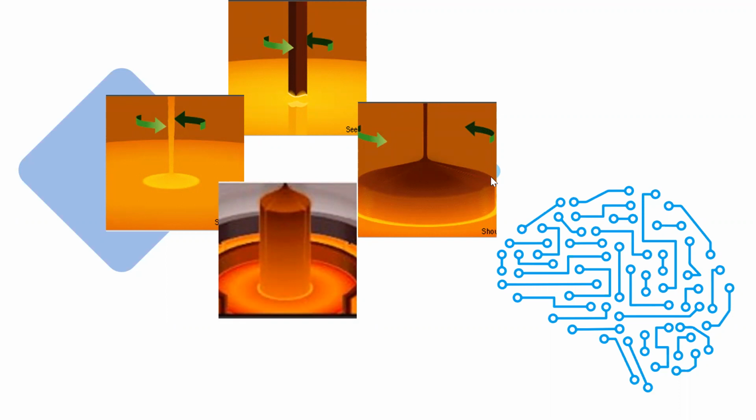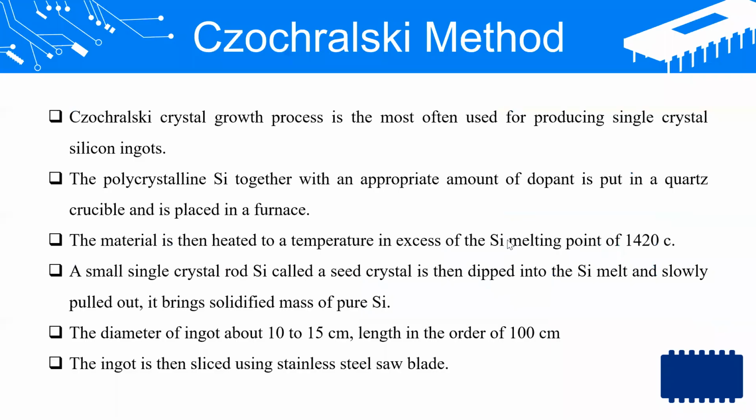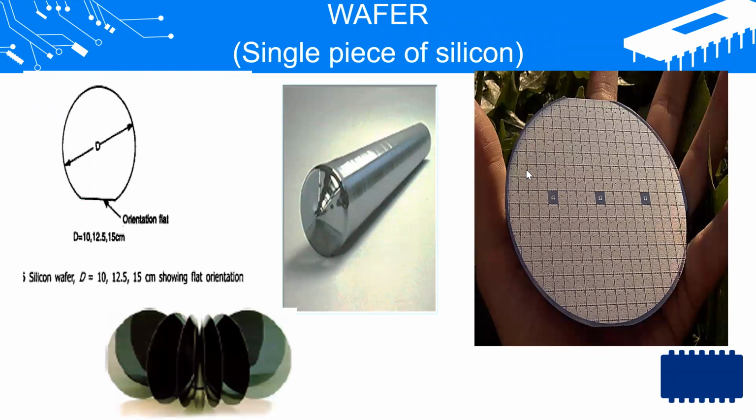The slices of the ingot are called wafers, and typically the thickness of a wafer may vary from 0.4 mm to 1 mm. This process is very important as it is necessary to maintain a flat plane and the desired surface orientation. If the sliced wafers are to be used for VLSI application, then before the etching process, a mechanical lapping process will be carried out. Using this process, wafers with uniform flatness are achieved, which are mostly required for photolithography.